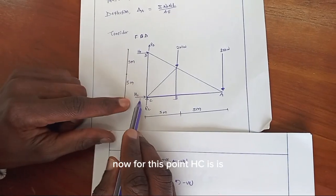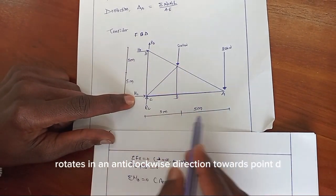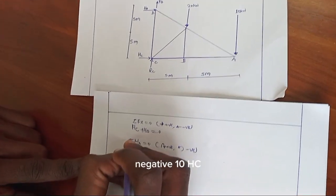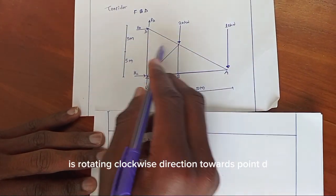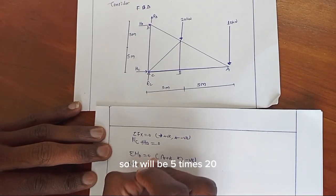Now, for this point, HC rotates in anti-clockwise direction towards point D, so it will be negative 10 HC. The 20 kilonewton rotates clockwise direction towards point D, so it will be 5 times 20